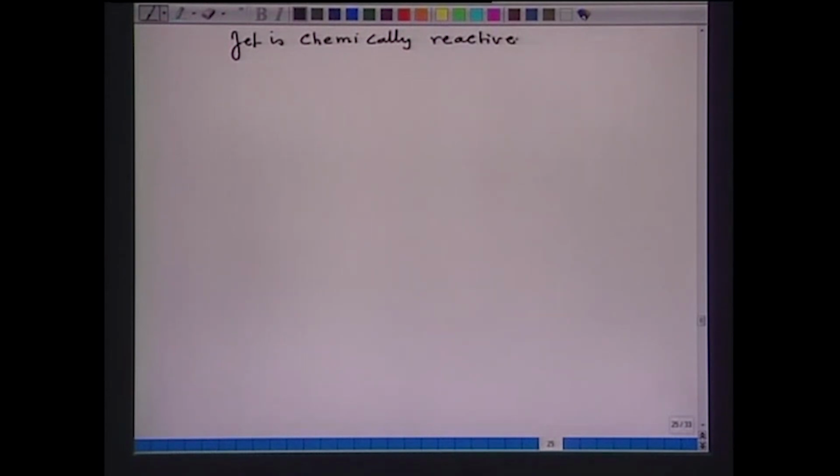then what do this soft jet and hard jet mean? A chemically reactive jet means, again, the jet has mass and velocity. So, mass of the jet will be consumed, or distributed, or diverted, and velocity of the jet will be used to create the mechanism for faster mass transfer reaction. So, in the light of soft and hard jet, what are the effects that it can induce into the bath?